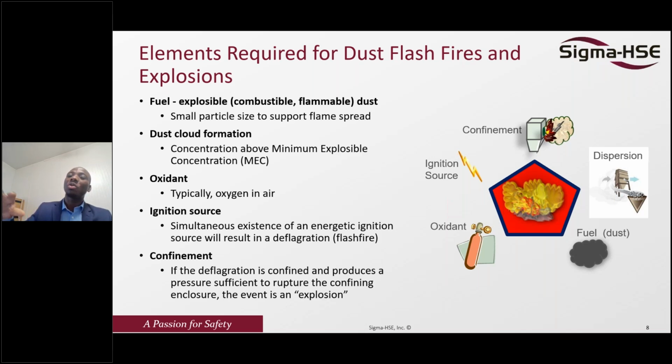Then we have homogeneous ignition: the energy that we release will actually create a vapor, and the vapor will react with oxygen to ignite. So homogeneous ignition, when dispersed in the air, acts like a domino effect, where maybe the first one ignites and moves to the next, and then we have a combustion. Each of this energy which is released can accumulate.